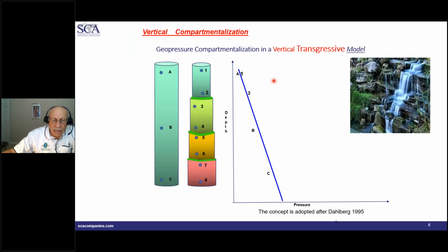This is a mechanical model. If we have a cylinder, fill it up with water, whatever, salt water or fresh water. Here is your gradient. By the way, the gradient is the change from one point to another point, it is not depth related. I have some slides on LinkedIn to explain the difference between gradient, which is the pressure over depth, or the gradient between 2 points. The gradient is between 2 points. It's not a value over depth.